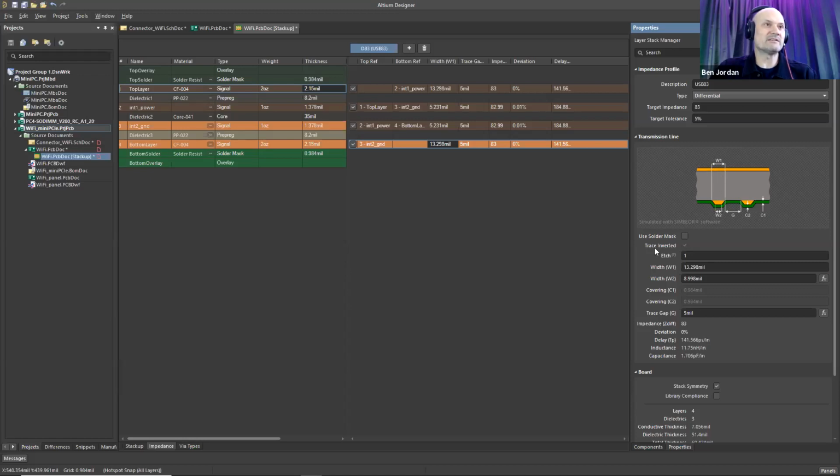It's on one side of the trace, and at high speeds, most of the current is traveling only in the thin layer of the surface because of skin effect and proximity effect. So it doesn't really profoundly change the dimensions of your trace in terms of width and gap.